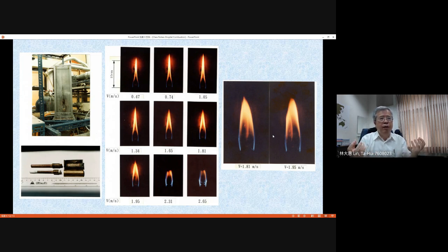They experience the same hot temperature environment, whether purely hot without flame or with flame. They have the same feeling, which means when you look at the droplet itself, we need to ask the same question: do we need to bring the combustion model into your spray simulations? This is a good question in the literature. People think maybe we just need to consider the evaporation of droplets at high temperature, which is good enough without considering the droplet diffusion flame mechanism.